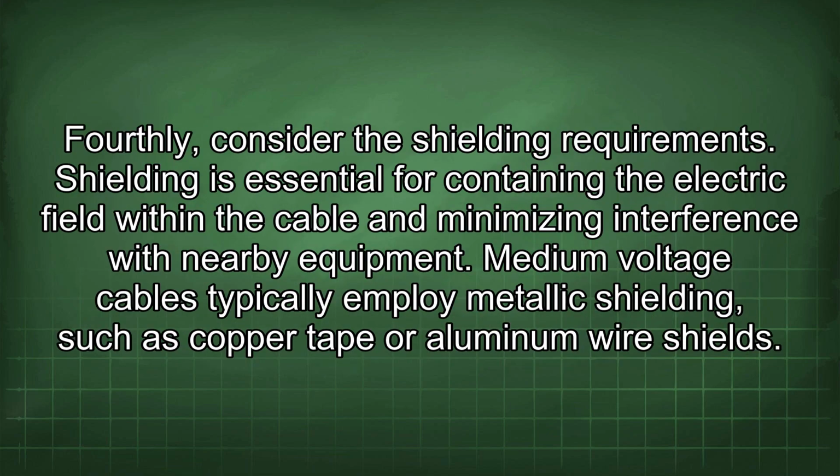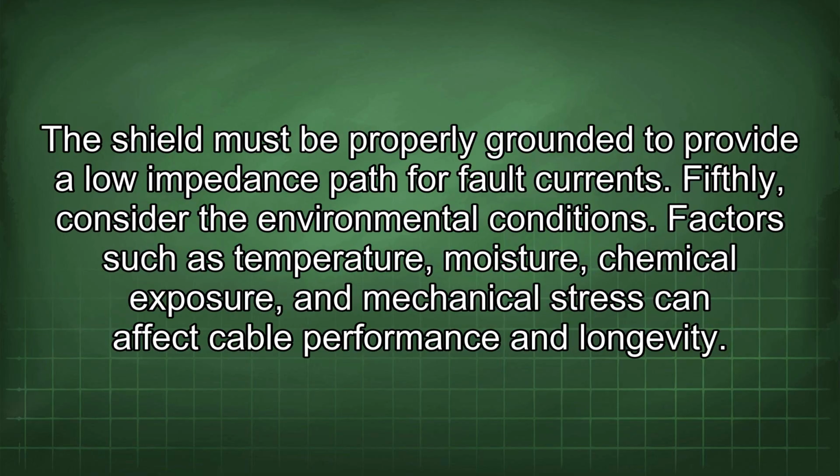Fourthly, consider the shielding requirements. Shielding is essential for containing the electric field within the cable and minimizing interference with nearby equipment. Medium voltage cables typically employ metallic shielding, such as copper tape or aluminum wire shields. The shield must be properly grounded to provide a low impedance path for fault currents.